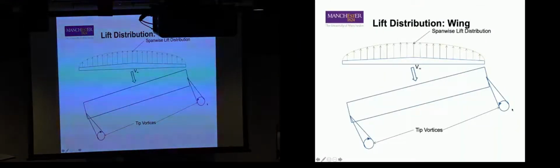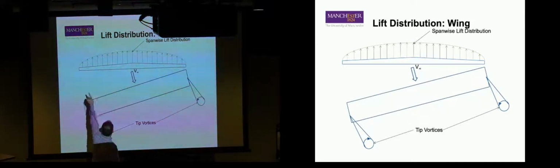There we go. Why is it the case that we produce no lift at our tip? Now, here's our wing. We're looking at it from either the leading edge or the trailing edge. That's the green lines with the arrow, what's called our span-wise lift distribution. And the reason it goes to 0 at the tips is the same reason that me talking to you doesn't generate entropy.